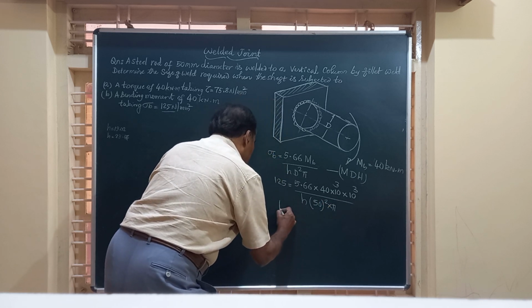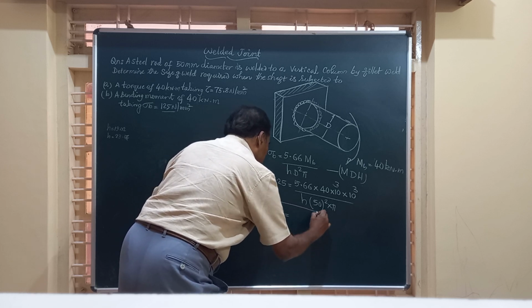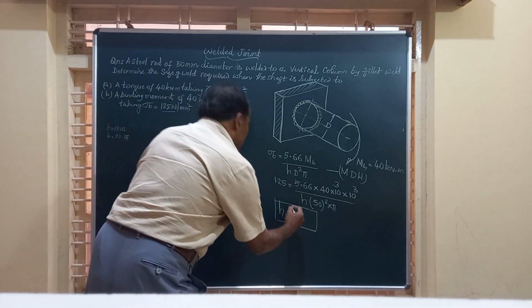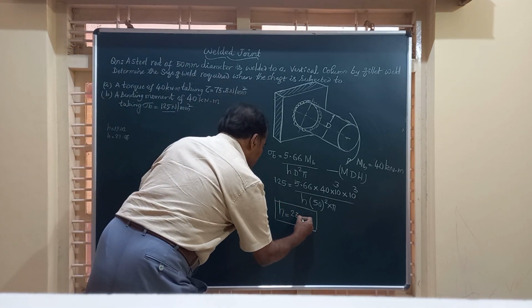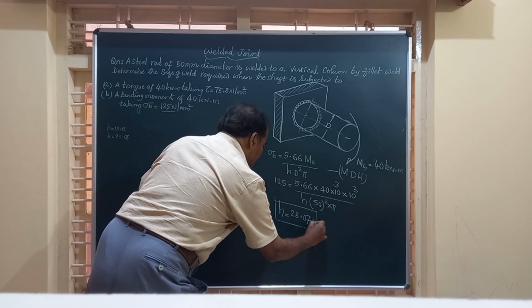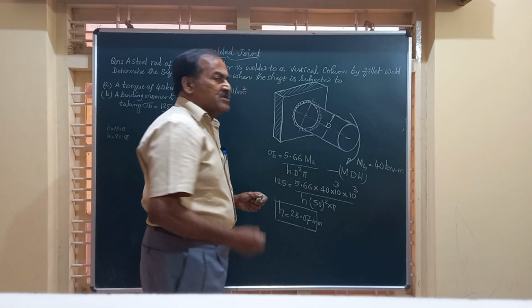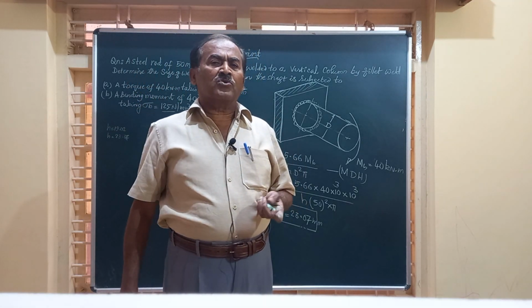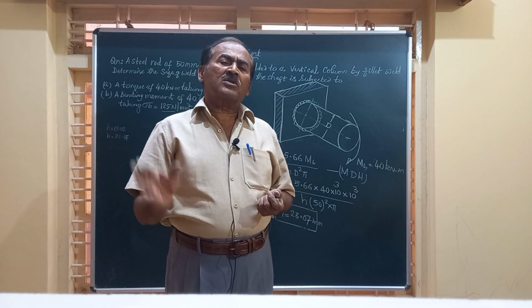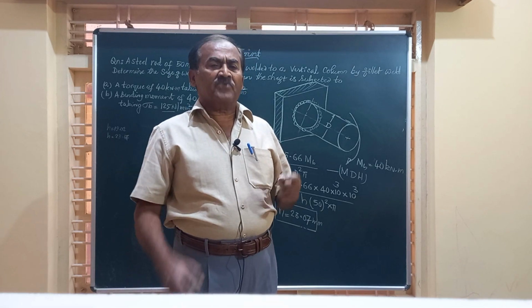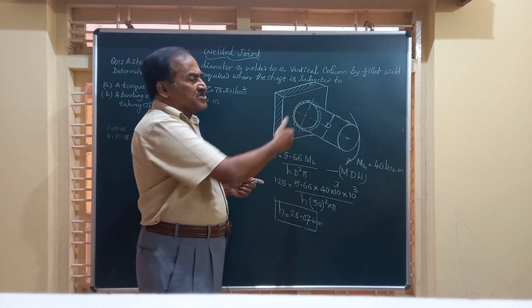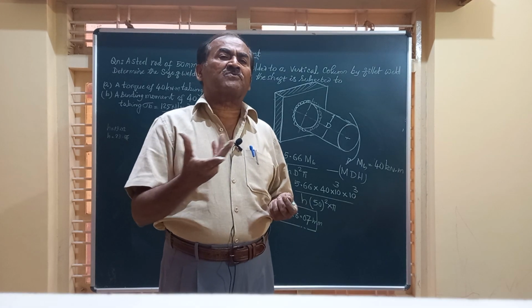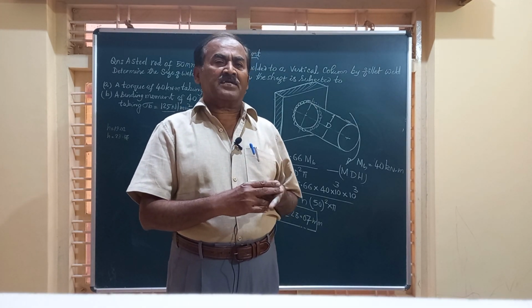If you simplify, you will get the value of this h, the size of the weld required in this case, as 23.07 millimeter. So friends, if you are very familiar with the use of the data handbook, you will be able to solve a lot of such problems, and you find a very big table wherein all such different cases of welding done on different shapes of members are given, and you can practice.